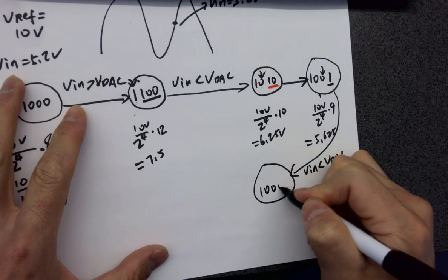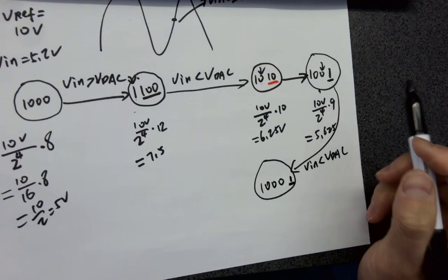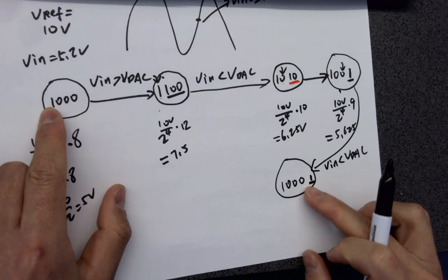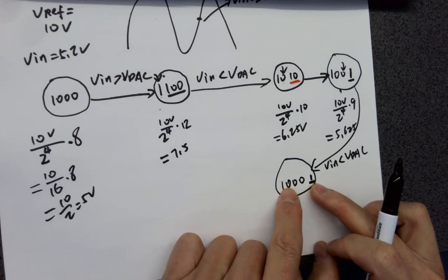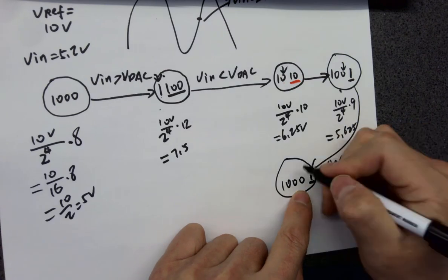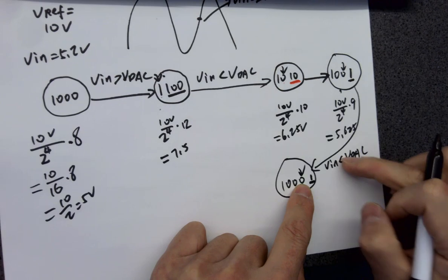One zero zero zero. Why? Because the 1 is being shifted out. You only have 4 bits holding the values. So the original 1 here has been shifted out and only leaves 1000 here. And that's a newly plugged 0 from this comparison.